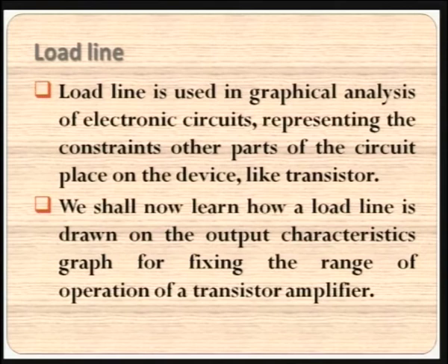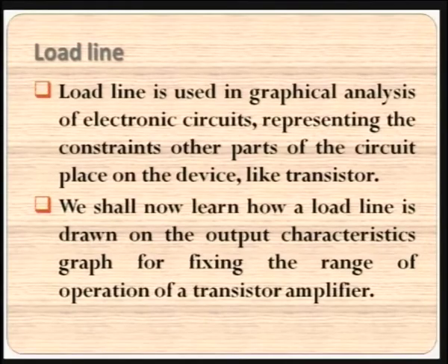The load line. What is a load line? It is very much used to fix the Q value. First, let us learn what is a load line and then how to draw a load line on the output characteristics curve. Load line is used in graphical analysis of electronic circuits, representing the constraints other parts of the circuit place on the device, like a transistor.